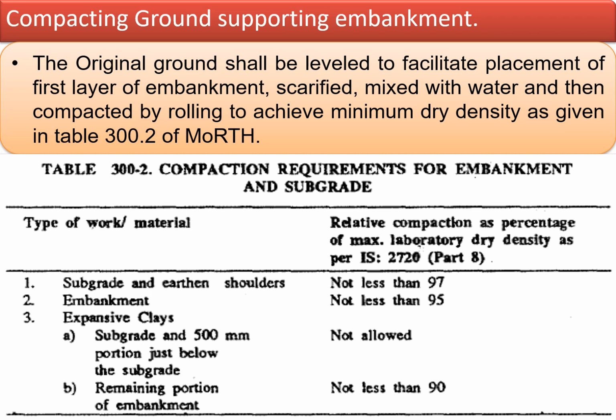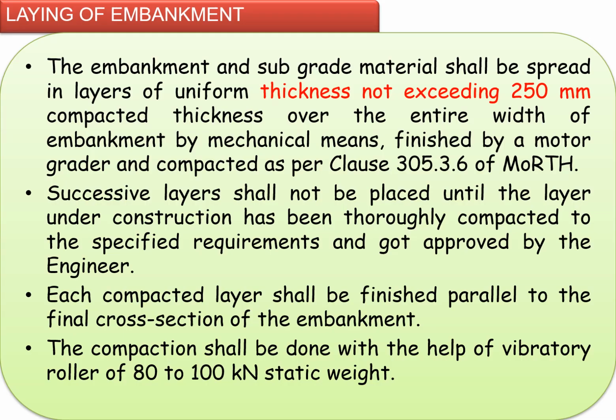For expansive clays, wherever expansive clays are present, in the subgrade and the 500 mm portion just below the subgrade, expansive clay materials are not allowed. In the remaining portion of the embankment, we can go with expansive clays where the compaction requirement is at least 90%.